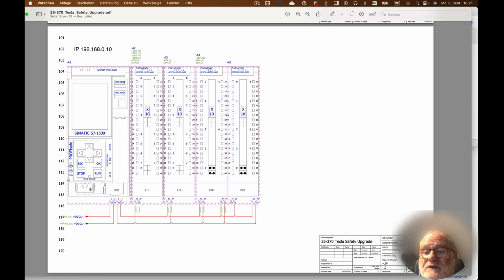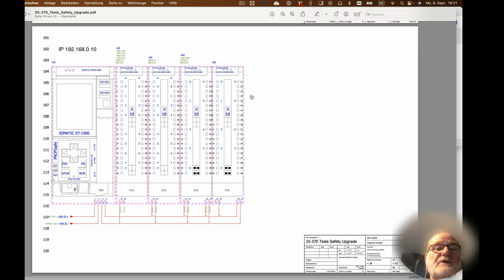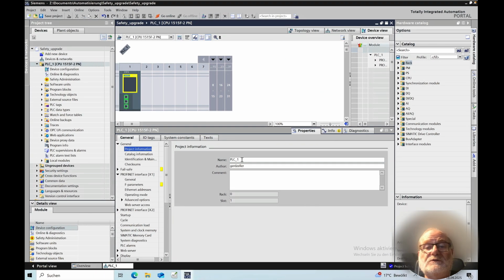So we will have the equal 28 plus S1 for the place where it's installed, and then the actual name of it. So we will have the equal 28 plus S1 minus KF1. This is the actual IEC normative name for a PLC.